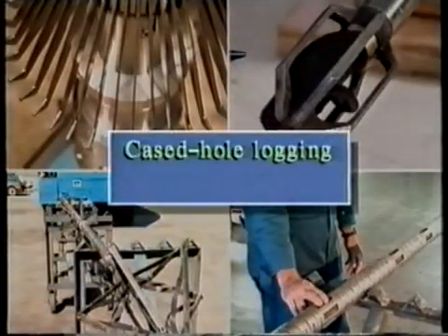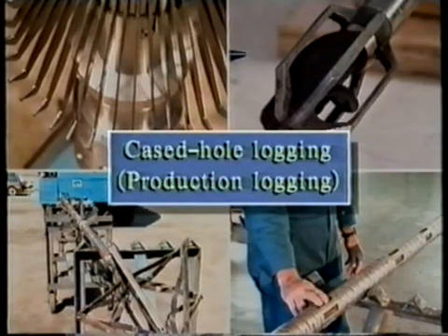In fact, we may also wish to use cased hole logs to measure the quality and continuity of the cement sheath that we've placed between the casing and rock formations, or to inspect the condition of the casing over time. And once a well's casing has been perforated for production, we may also need to run cased hole logging devices to measure the relative amount of fluid being produced from any given zone. Many of these cased hole logging devices are also termed production logs, since they are run during or after the well's completion phase, when the well becomes the production department's responsibility.